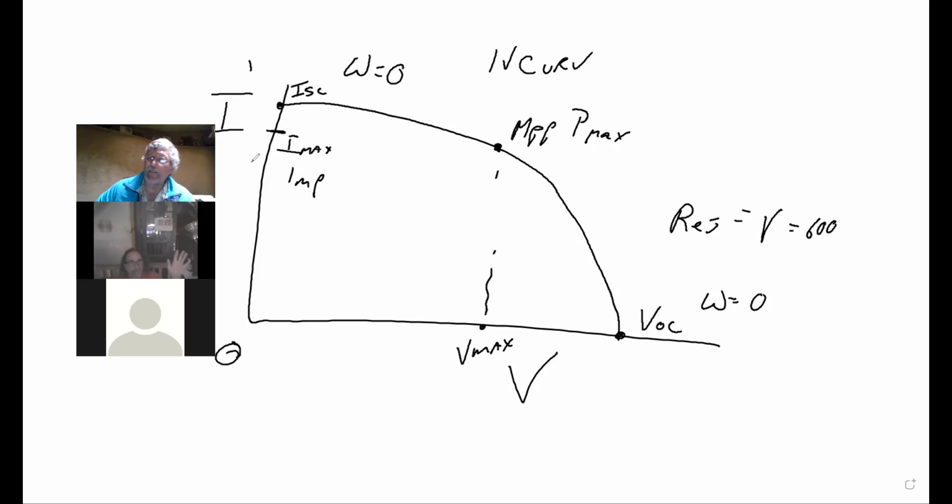Yeah, John, you had a question? Okay, so if you put a clamp on amp meter while you shorted the panel out, would it be reading the maximum amps? I mean, I'm kind of having an issue with this because you have maximum current with no voltage. So is there current flowing or not? I think the ISC has to be a theoretical number.